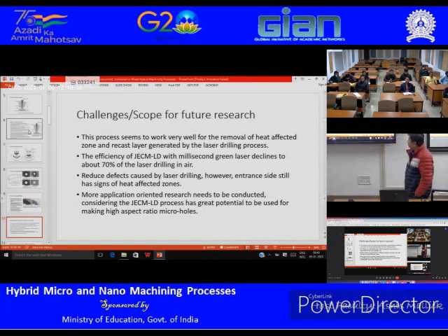So challenges. What are the challenges? I really think that the process works very well for the removal of heat affected zone and recast layer generated by the laser drilling process. Now you need to see how much the speed is going down, right? And that is something that you need to think about. I said 80%, but in fact it is actually 70%. So that means the material removal rate or the speed decreases about 30% because the efficiency of the laser actually is reduced by 30%.